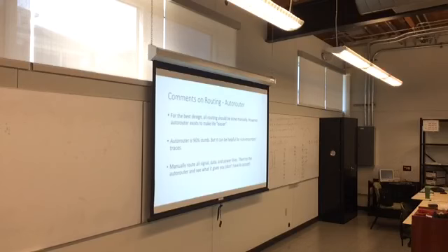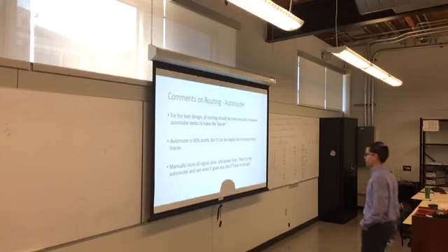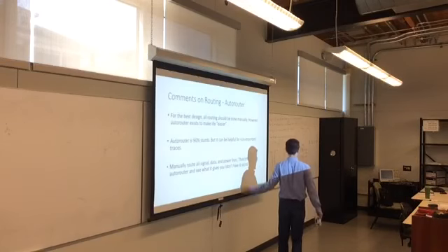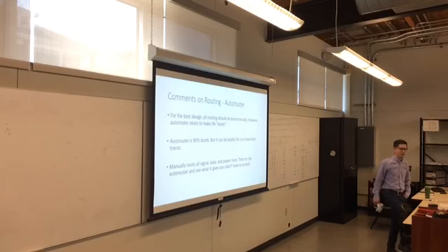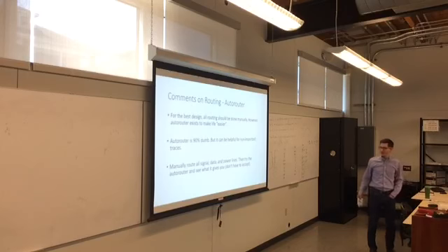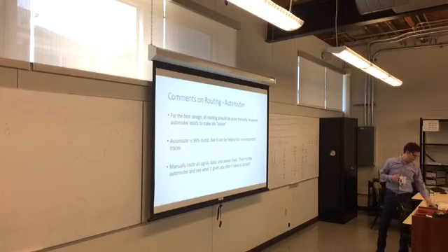It's going to route signals around each other. I would avoid generally using the auto router. So you should manually route the signal, the data, and the power. And then if there's something left, you can try the auto router. You don't have to accept its solution. You can always reject it. So people like it. They click auto route. It gets done. It will give you a solution. The solution may be terrible, and it may not be good, but it will give you a solution.